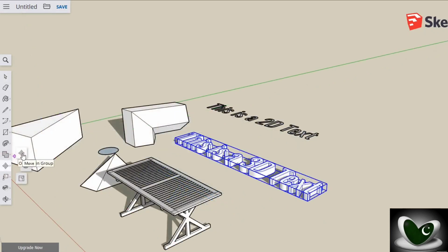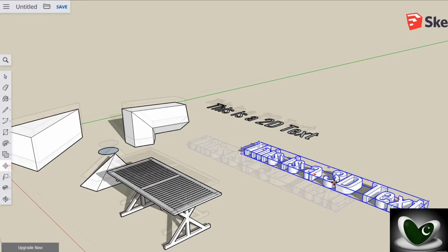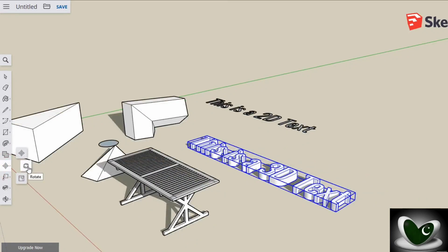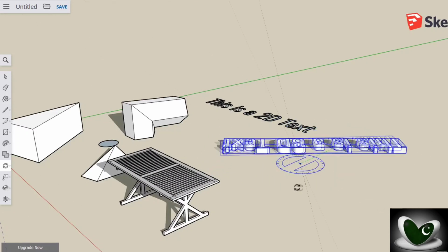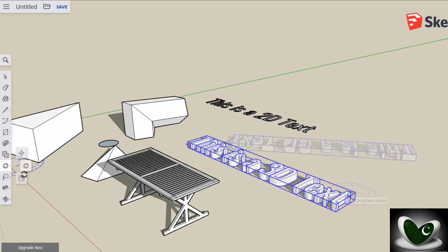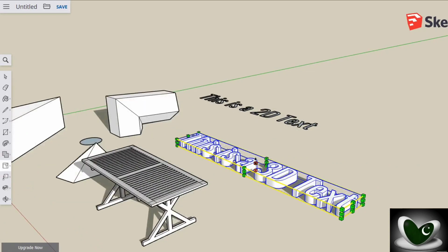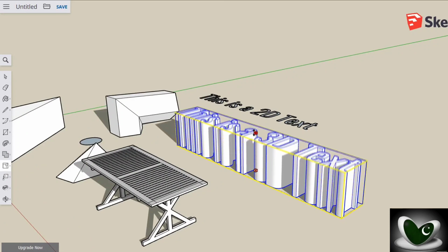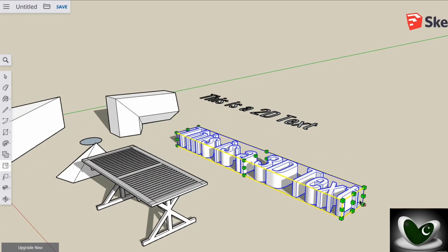Use the Move tool to move selected objects where you like. Whereas choose the Rotate tool to rotate these by fixing the main anchor point and then the rotation angle. You will rotate on the ground plane when the goniometer is shown in blue color. Enable the Scale tool to scale the object by clicking and dragging couples of cubes toward different 2D and 3D directions.